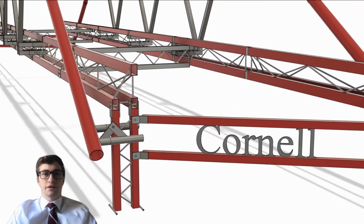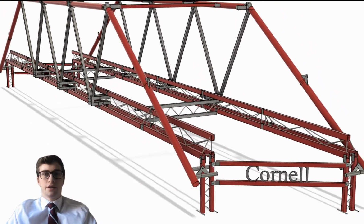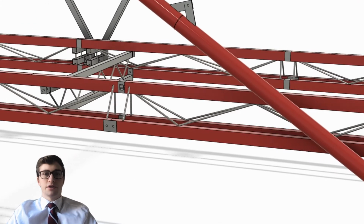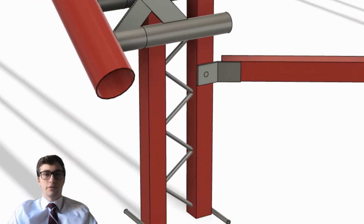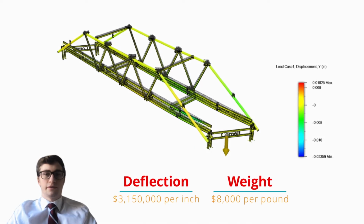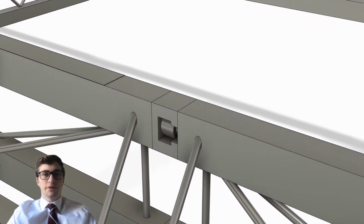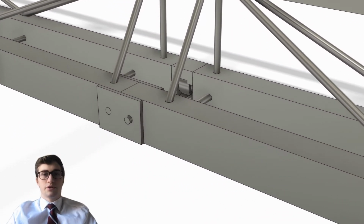Of course, we do not deliberately allow these disadvantages to slide if they are not counterbalanced by advantages. The bridge's heavy weight is offset by its extremely low deflections. Having trussing, the space frame, lower laterals, and even legs all contribute to the structural strength of the bridge. These low deflections justify the large weight because the structural cost of the deflections greatly outweighs the structural cost of the additional weight.